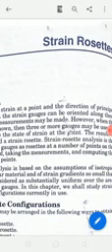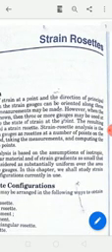If you want to measure strain in the x direction, the y direction, or some other direction, you have to orient a number of strain gauges. Then you take those readings, consider some equations, and find the strain in a particular direction as well as the stress in particular directions. So arranging gauges systematically along any direction, we can call a strain rosette.